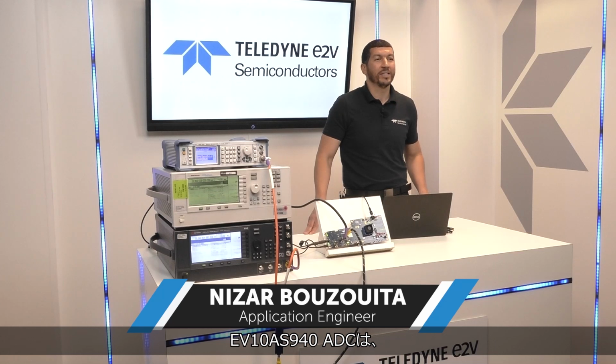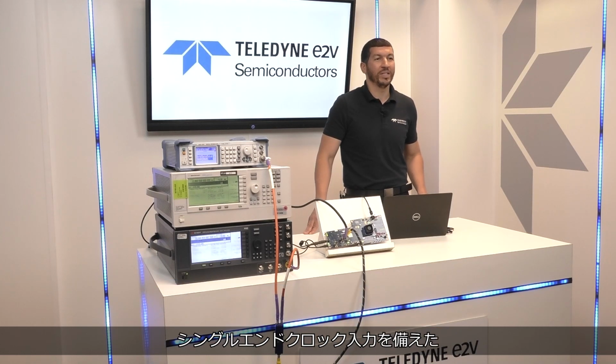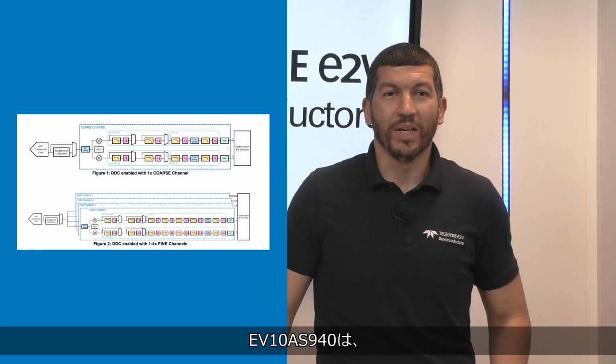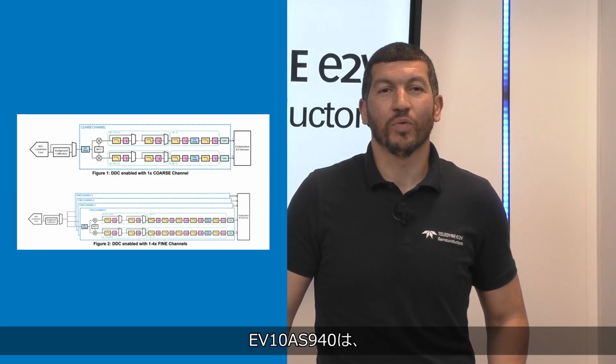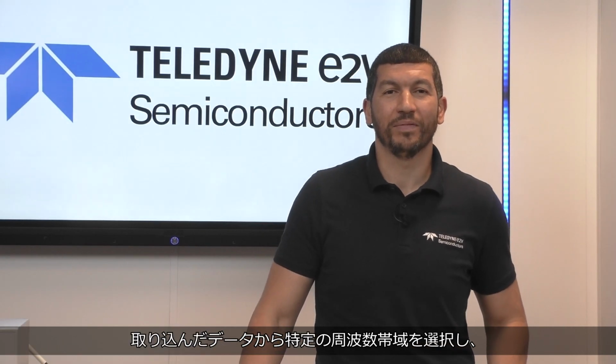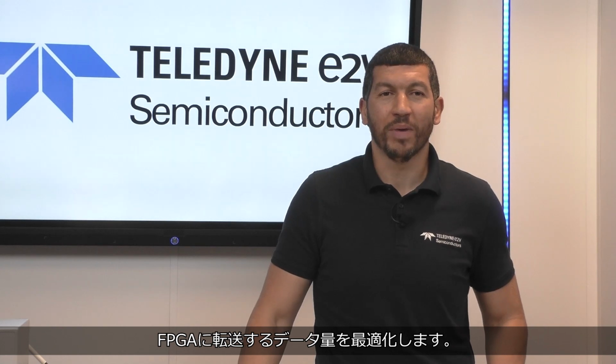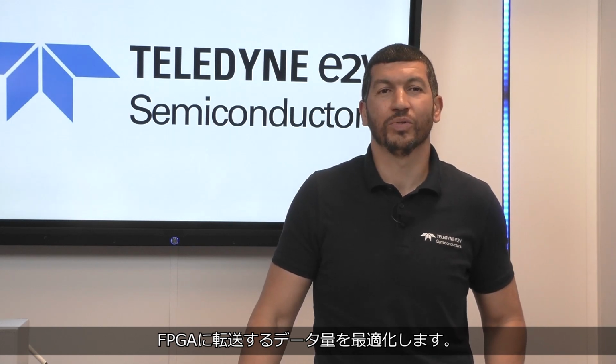The EV10AS940 ADC is the most advanced microwave capable ADC with large input bandwidth up to 35 GHz, a single-ended analog and clock inputs including digital features. The EV10AS940 offers digital down conversion capabilities to select specific frequency band of interest from the data captured and optimizes the amount of data to transfer to the FPGA.